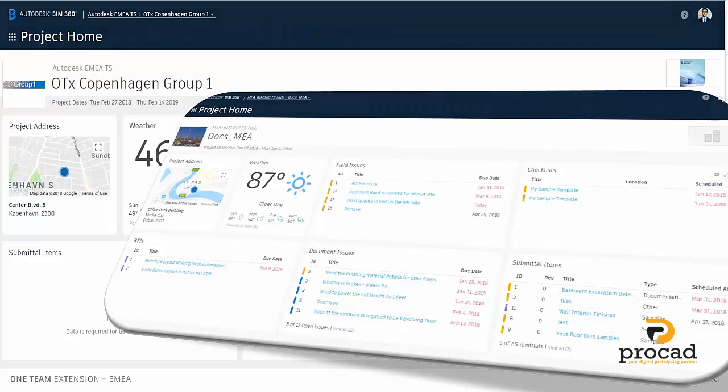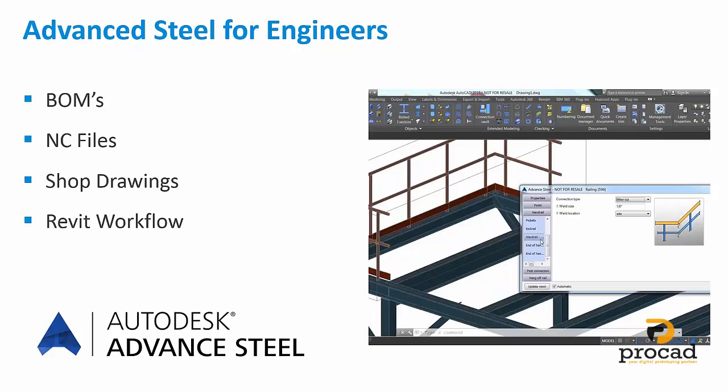So looking at some design tools for engineers, there's also Advanced Steel, which allows you to create shop drawings, automated bill of materials, and there is a workflow from Revit as well. So it's not just architecture I'm focusing on today, but also looking at the entire part of a design project as well, and everybody that's involved. This can also be outputted to NC files that are used for CNC machines, a common format that's used out there as well. And that's just an example of Advanced Steel, and the screenshot shows a railings and some steel platform there as well.